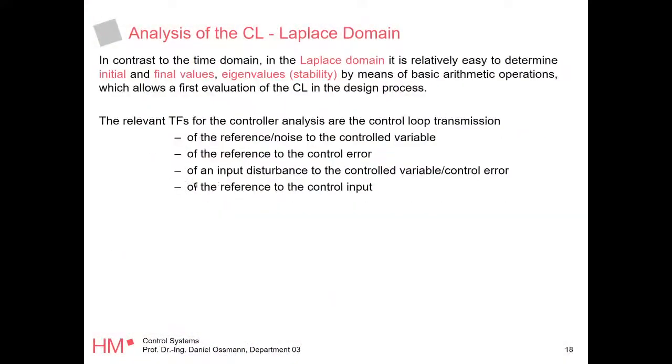This is why we're obviously going to do that in the Laplace domain, where things are much easier and we can do that on paper, right? So we don't need to think about coding it up, because we only code it up when we already have a good knowledge about our system, right? So you can see this as a preliminary step. We're going to do this in the Laplace domain because we can easily assess stability, we can easily determine initial and final values for certain inputs, and we only need a handful of inputs.